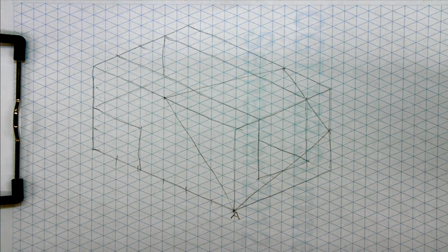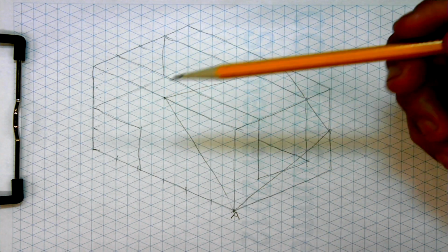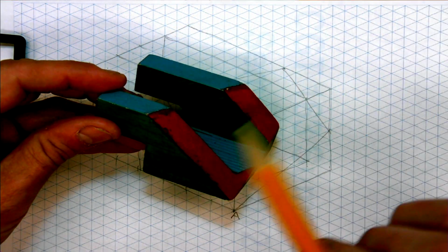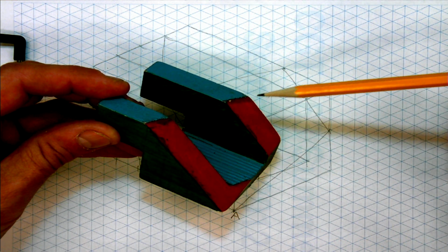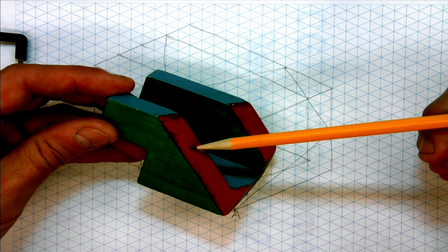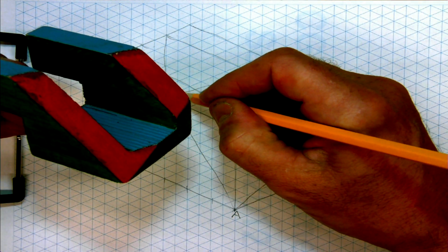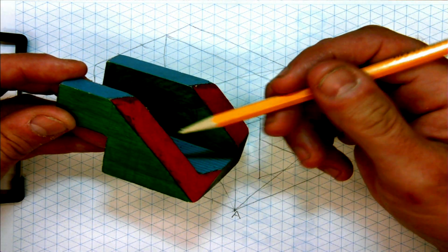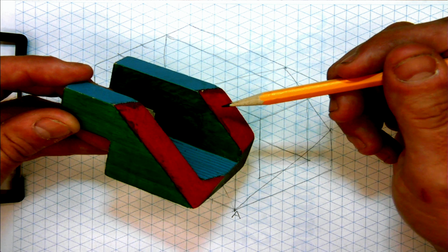So now, we've got to look at what I'm going to term spatial relationships here. You have a frontal plane here, okay? It's cut by the incline, or excuse me, by the oblique plane. So notice on this that this line here and that line there are parallel, that line there and that line there are parallel. In other words, wherever, in this case here, this oblique plane, the red one, intersects a frontal surface here defined by point A, B, then all these frontal planes that are cut by the oblique plane will form parallel lines, okay?